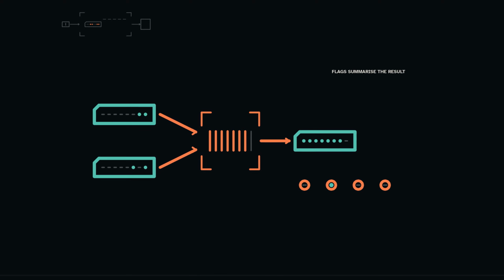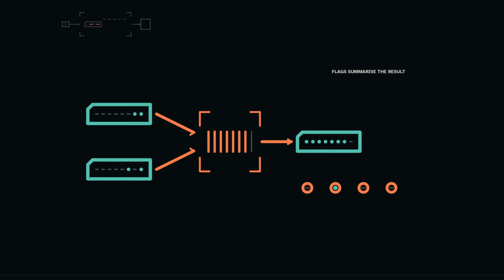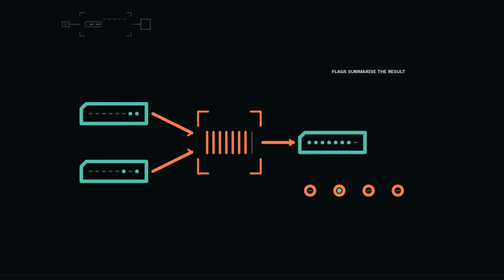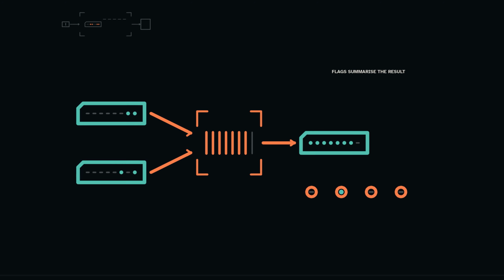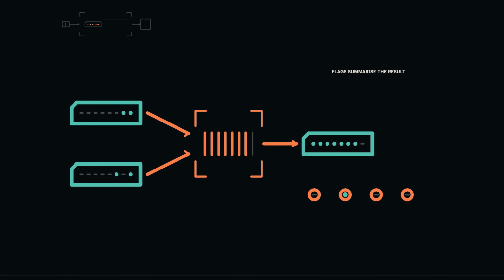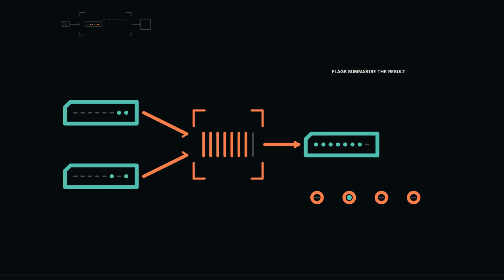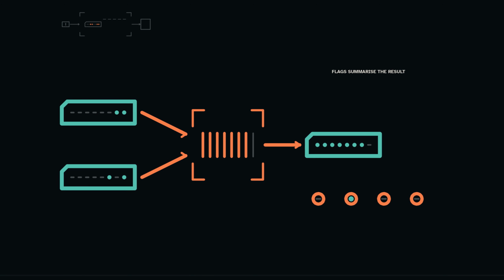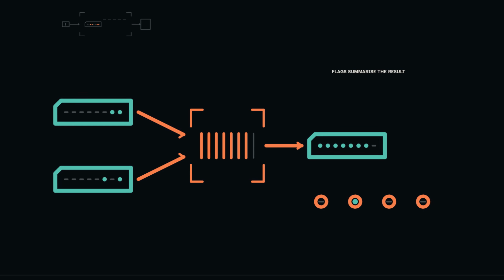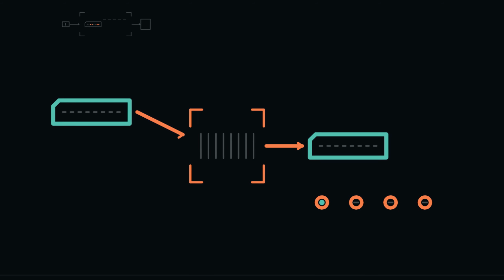Subtraction can reuse addition circuitry by forming a 2's complement negative of the right operand and adding it. The 8-bit result still wraps modulo 256. SE8 defines carry after subtraction as no borrow. Carry is 1 when the unsigned left operand is at least the unsigned right operand. That convention must be learned rather than guessed from the word carry. 3 minus 5 stores hexadecimal FE, which can be read as unsigned 254 or signed -2. Carry is clear because an unsigned borrow was required. 4 1-bit flags preserve compact facts.